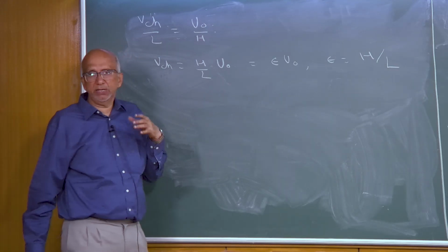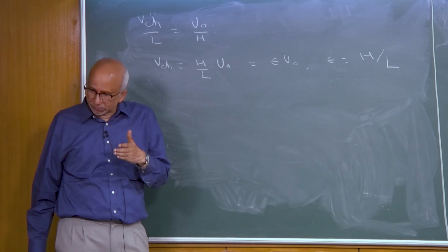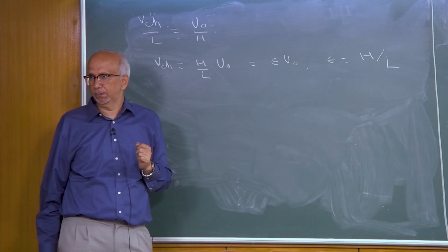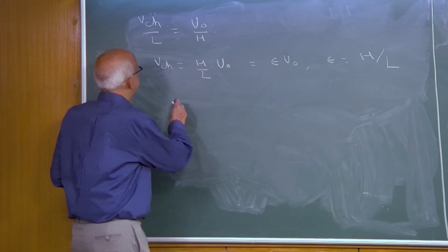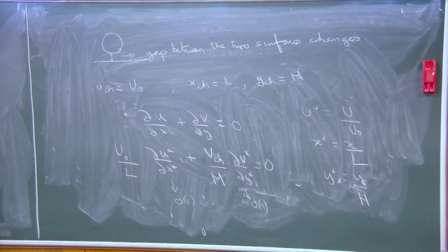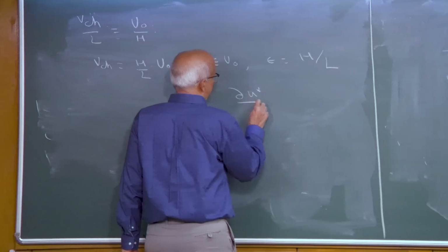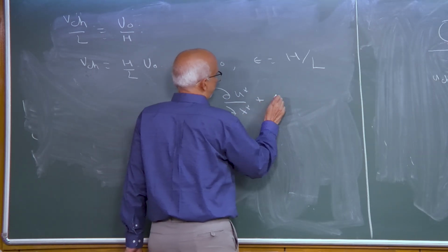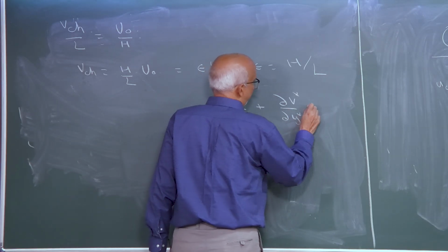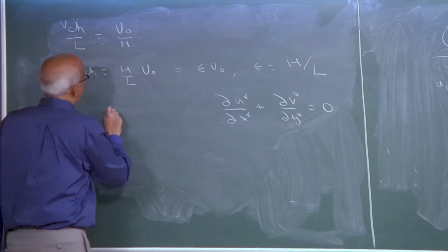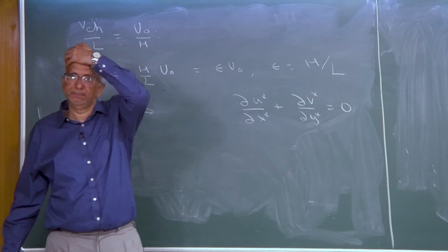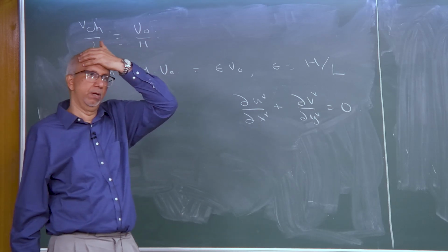So from this we basically conclude that the velocities in the transverse direction to the flow are negligibly small. That is the inference. Only if I choose the v characteristic like this will my dimensionless equation of continuity be this. This choice of v characteristic ensures this, and my two terms balance.